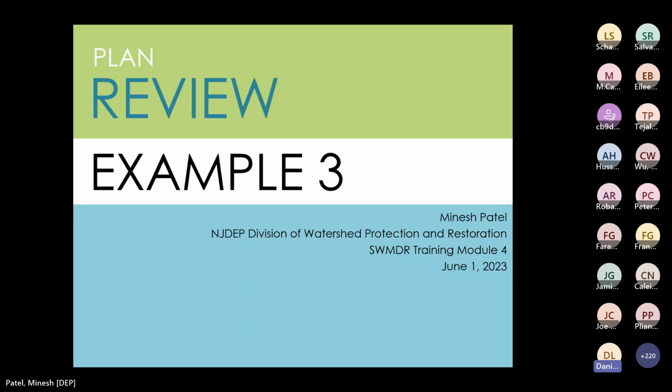There's really no motor vehicle surface that gets water on it. In that case, as we said, you may have the underground infiltration basin with a detention component to provide water quantity control. We have been seeing a lot of stormwater chambers. They serve as the water quantity detention component. They've been installed in the underground infiltration basin to meet the requirement.